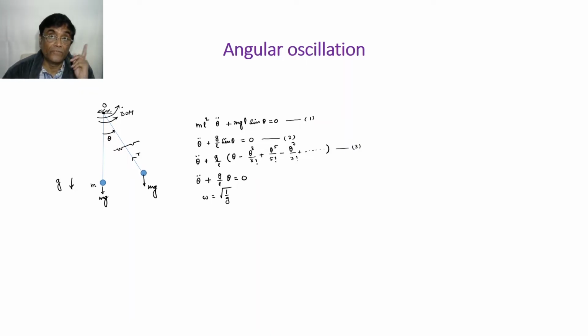There it was an inertial force, here it will be an inertial torque, and there it was mass times linear acceleration; here it will be inertia times angular acceleration. This is the inertial torque acting on this. Under these forces, the pendulum is in a virtual static state, so all the static equilibrium conditions apply. That is D'Alembert's principle.